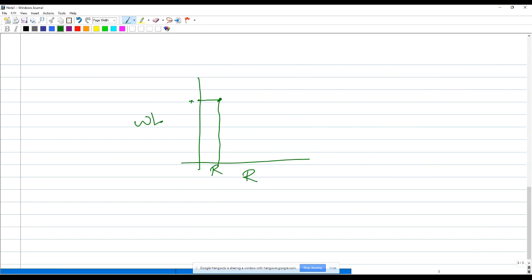Now, as you decrease the distance between this probe coil and the surface, these eddy currents will start getting induced on the sample surface, right? So that means some amount of current will be drawn to induce this eddy current onto the sample surface. In other words, some amount of energy will be taken up from the primary coil, which is in the probe, to induce these eddy currents, right? So as a result, the current or energy in the coil will reduce.